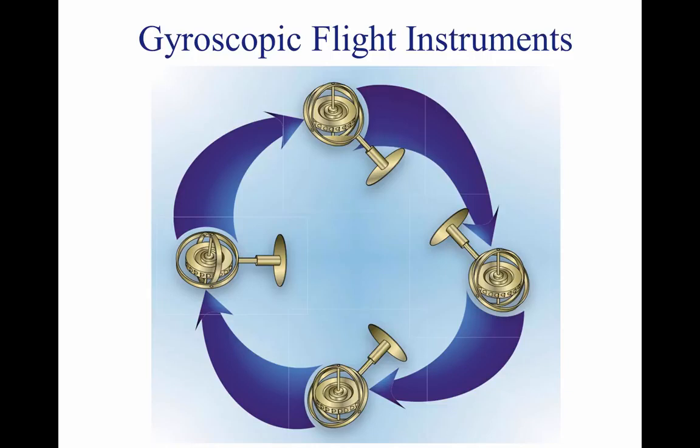There are two general types of mountings. The type used depends on which property of the gyro is utilized. A freely or universally mounted gyroscope is free to rotate in any direction about its center of gravity. Such a wheel is said to have 3 planes of freedom. Restricted or semi-rigidly mounted gyroscopes are those mounted so that one of the planes of freedom is held fixed in relation to the base.